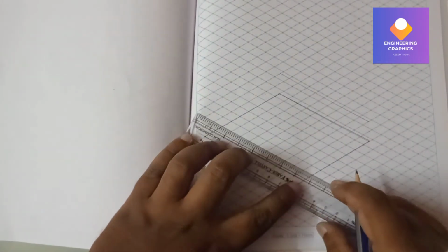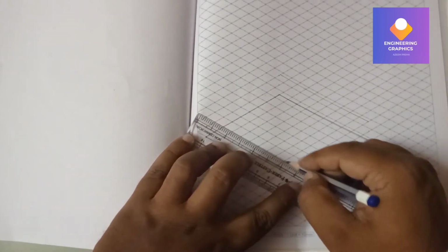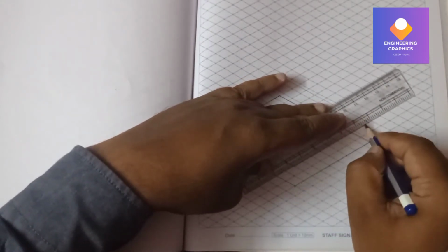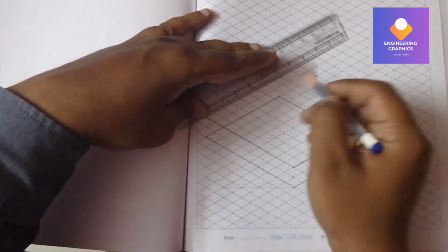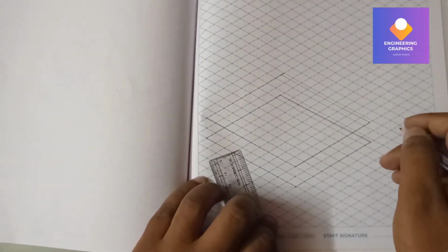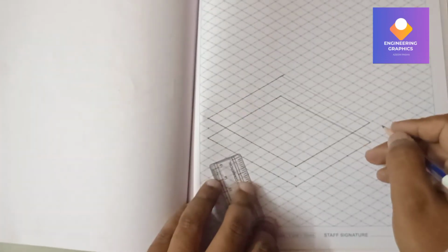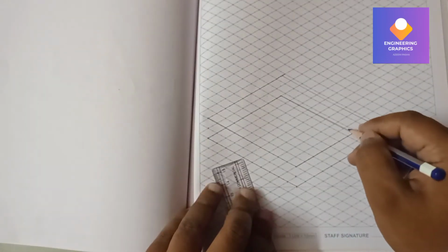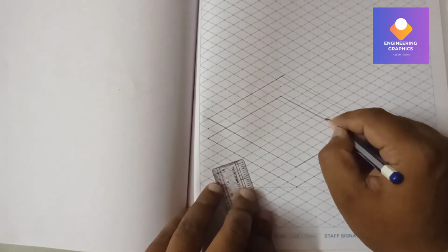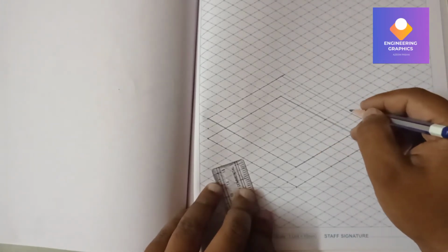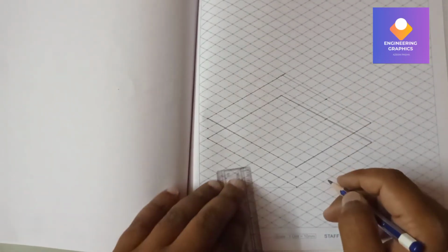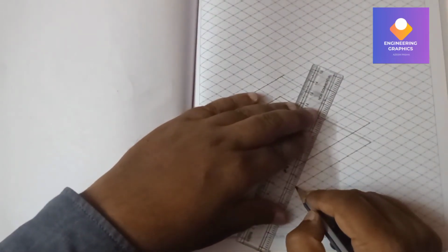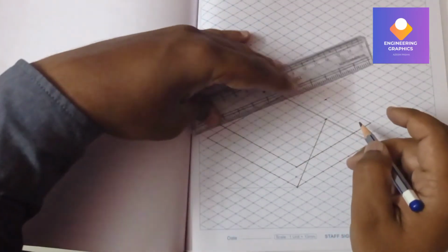Because it is a prism, we should get a triangular face on these two rectangular faces. So we'll be constructing another rectangle of dimension 100 by 86. Here we have to mark on the 100 mm side exactly the middle point, 50, because it is a triangle. Same thing I'm doing for the top face also. Count exactly 5 boxes and mark the middle point, then join with the other edge. You can do it.